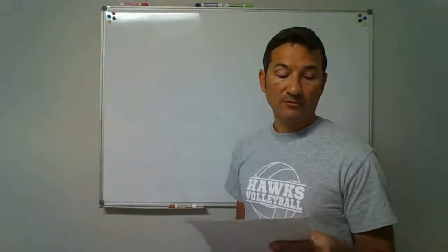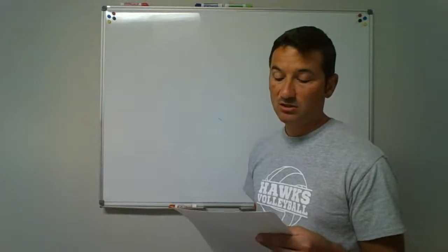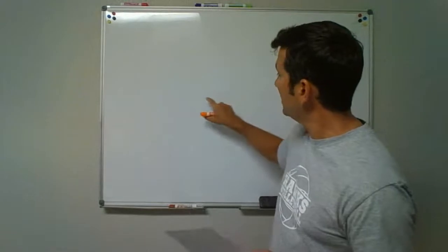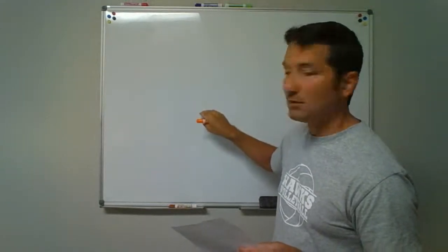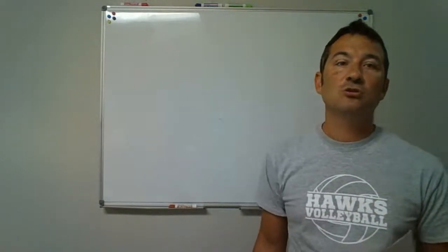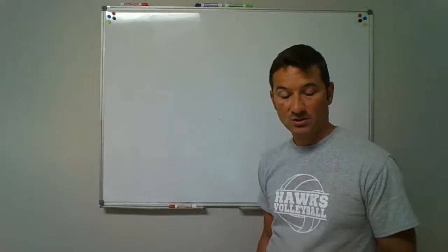Number 4, when boring a hole in a joist, how close can you come to the top or the bottom of the joist? We drew a floor joist and we said, you've got to stay out of the top, how many inches, and bottom, how many inches? When you drill that hole, it can't be any closer than 2 inches to the top or bottom was the answer.